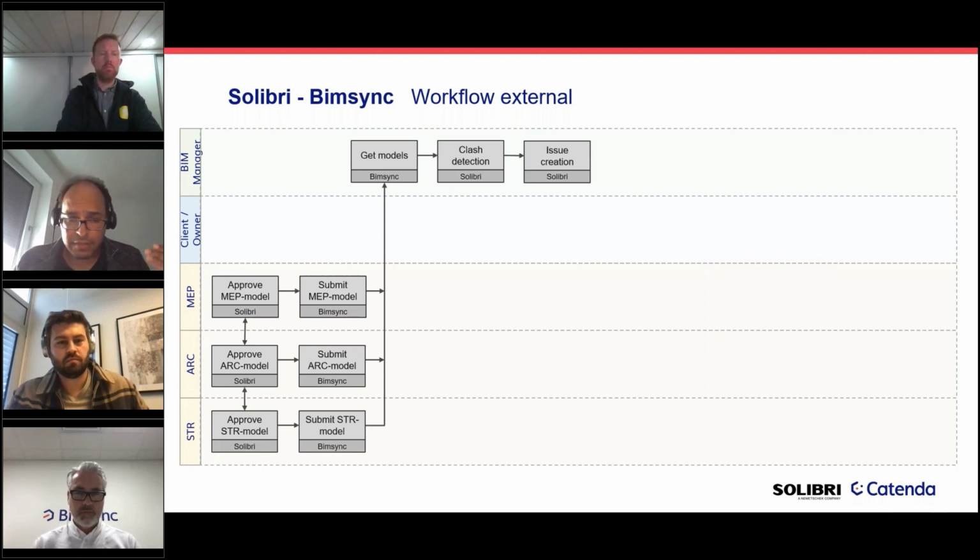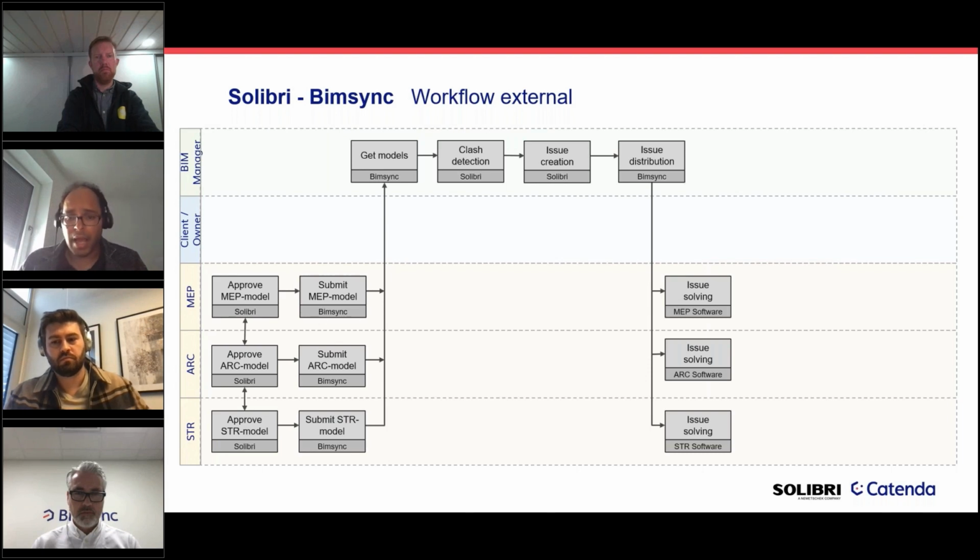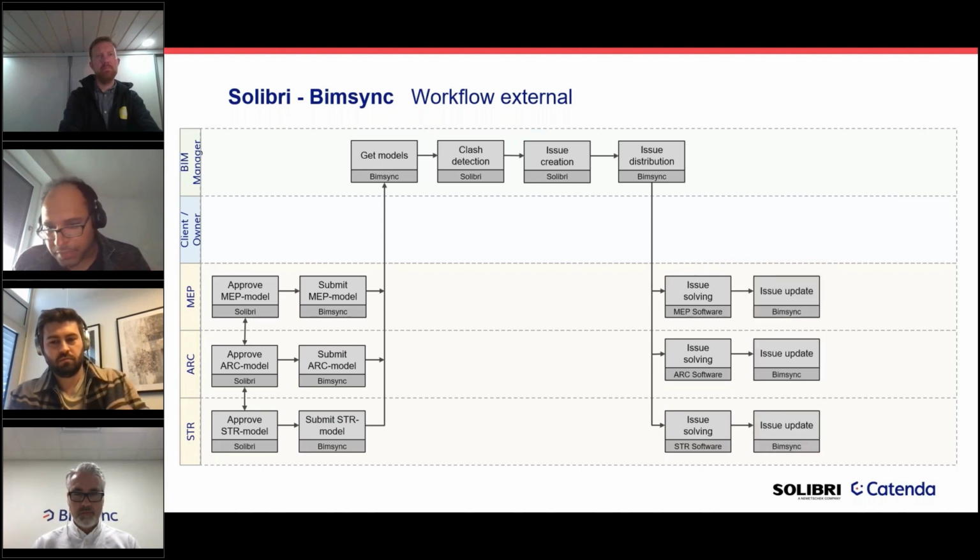After David does his clash detection, he would do the similar process of creating issues. He would distribute the issues, in this case, to me. I will then go and solve these issues, or this one or two issues, whatever the case may be, in the authoring software. Update my issue so that Bimsync knows something has happened to this issue.